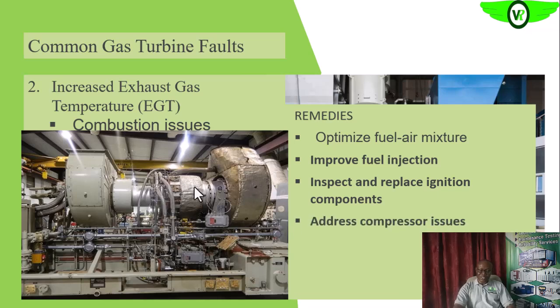Then once we have compressor issues, we want to take care of them. Operationally, we can take care of a surge or stall. The inlet guide vane is there to assist us in controlling surge. Then the bleed valve is also there for us to control such abnormal conditions during normal operations. So in our training on startup, we'll see the function of the bleed valve during startup, what it will help us to achieve.